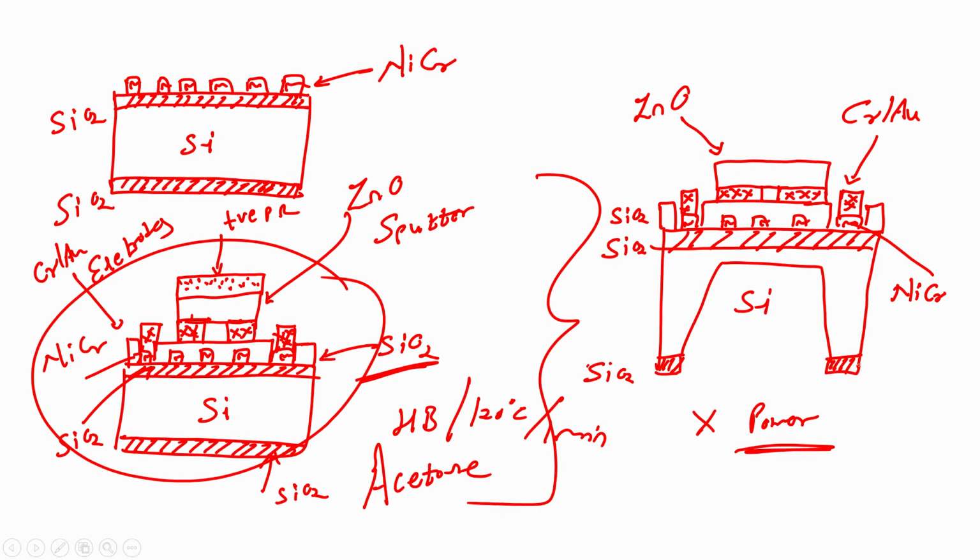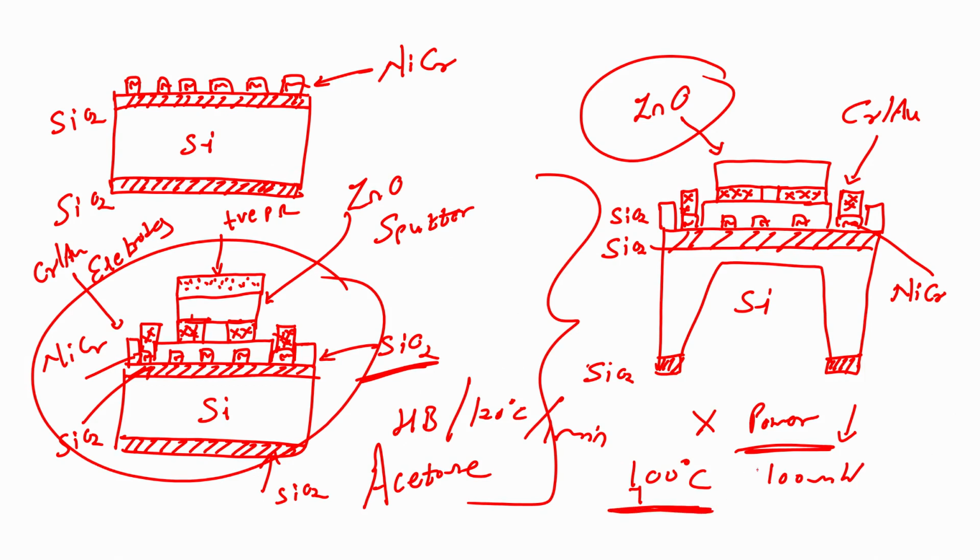Okay. Now I have to heat a thin layer of silicon, and that is why my power to heat the semiconducting oxide will reduce. So, to obtain, let us say, 400 degree centigrade, earlier we required, let us say, 100 milliwatt of power. Now, for the same temperature, if you want to reach 400 degree centigrade, I will require less amount of power because of my micromachining.